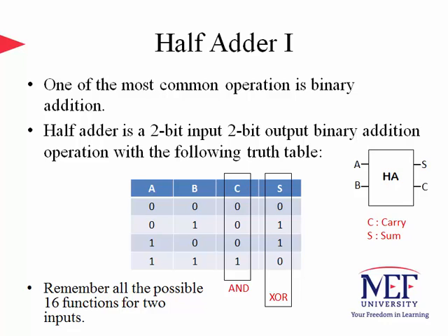In other words, as long as we do not have any overflow, the sum will be the binary sum of 2 bits. In case we have an overflow, that's the last row in the truth table you can see in that slide, that is to say A and B both equal 1. In that case, an auxiliary variable is needed to overcome the difficulty. That new variable is called the carry, also represented by the literal C. The carry happens only if both A and B are 1. It's also when the overflow happens.